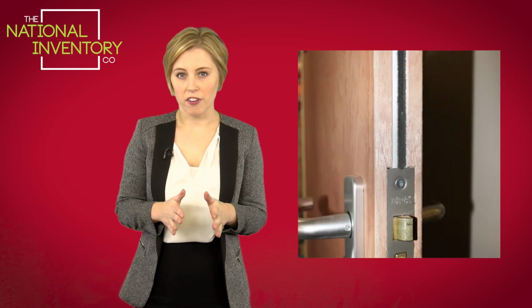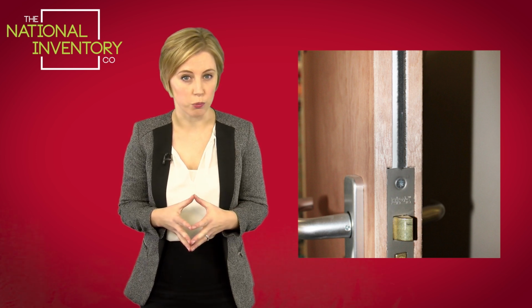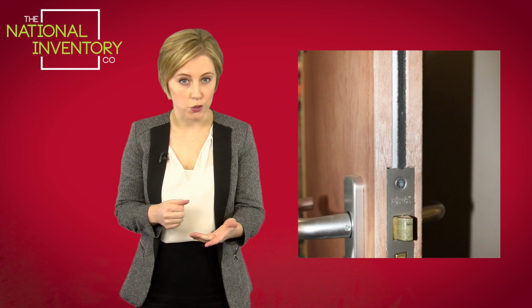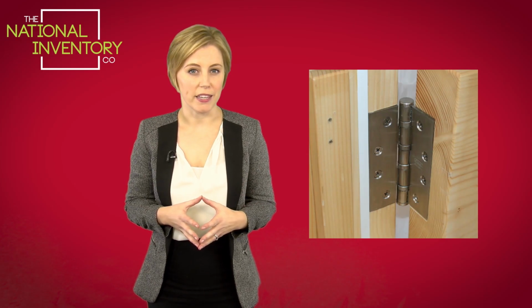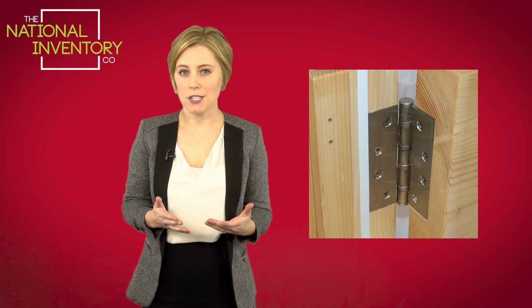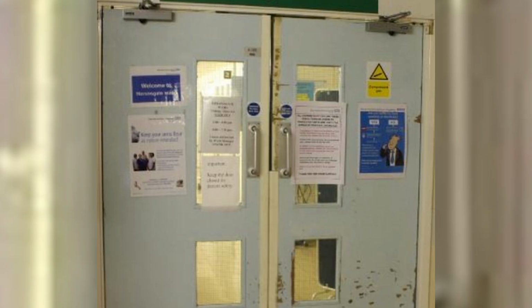Please note that some fire doors can be decorative and they're not traditionally heavy in a residential property, whereas commercial fire doors are a lot heavier. Fire doors always have 4 screws where the hinges sit, whereas standard doors will only have 3 screws. Also note that fire door handles or hinges will need to be fire retardant, so it's imperative that you do not change the locks or handles that they are supplied with, unless you're going to replace them with a fire retardant product.